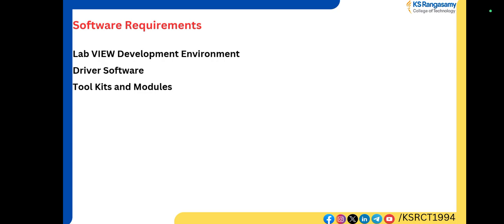So NI DAQ Max is for interfacing with NI DAQ hardware. The instrument drivers like VISA, IVI we can use for third party instruments. Then the toolkits and modules. The toolkits and modules are mainly used for signal processing.